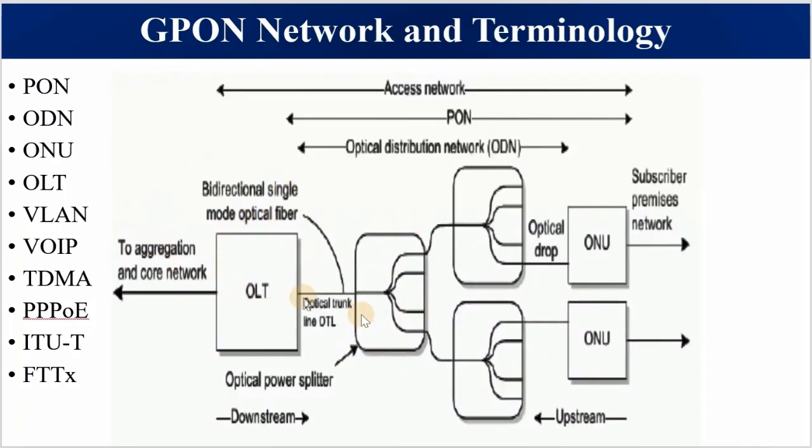This is a splitter. We've got one fiber incoming and various fibers coming out of the splitter. So this is a splitter, and it can be 1:32, 1:64, and we are now moving towards 1:128. You can have two splitters connected as shown, from one splitter to another splitter. We are going to look at the advantages of each and the disadvantages of each.